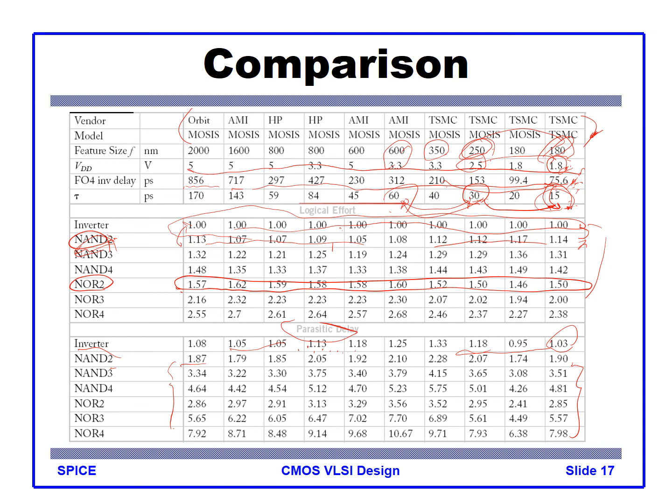So when you design a logic block, you can just use inverter and NAND 2. That's a way to design a faster building block. Any building block you require, you can always convert with NAND gates and inverters using the bubble pushing technique.